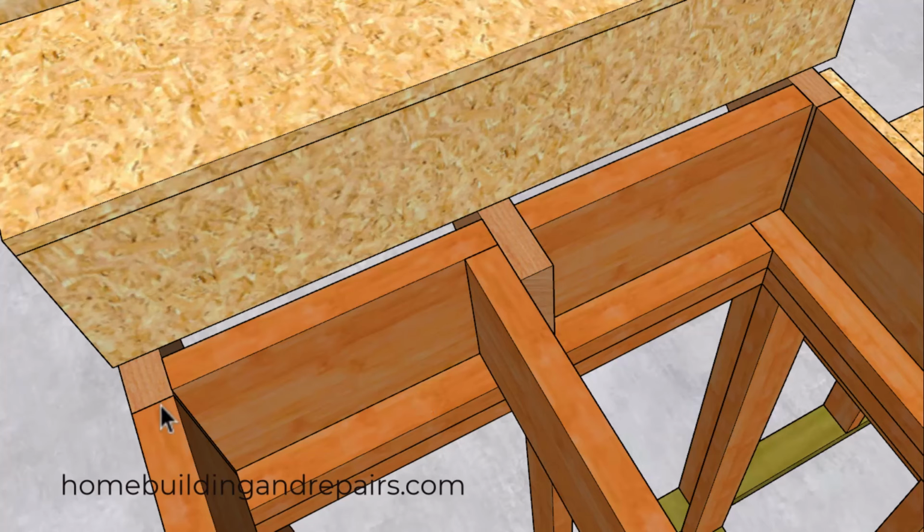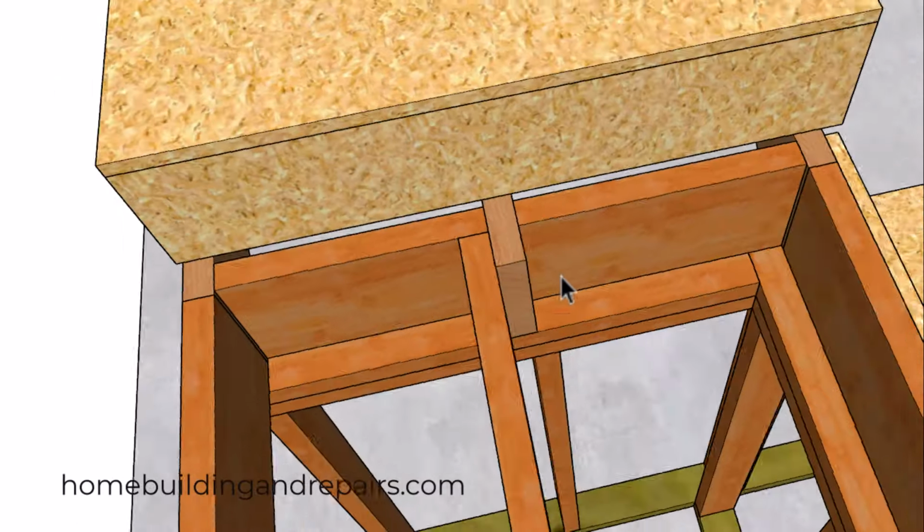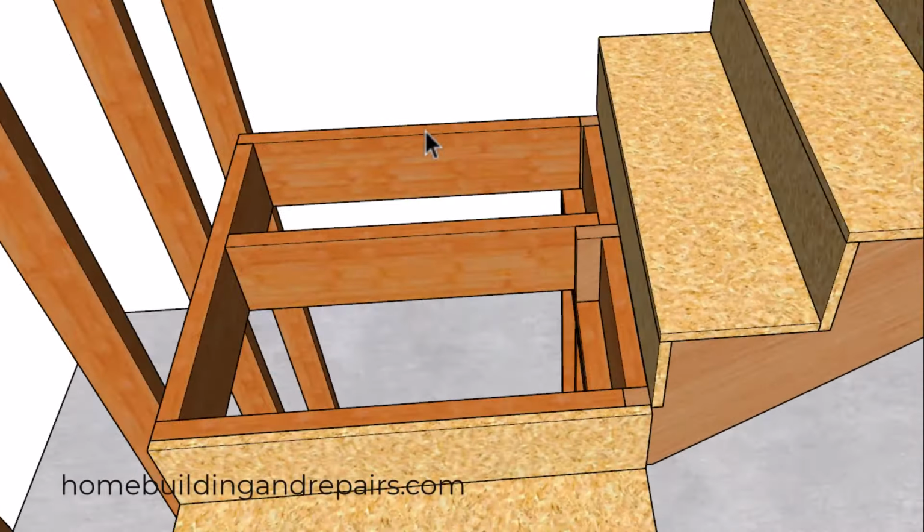And you can butt the joist to the stringer or lap them and then install your blocking. And if I was going to run the joist in this direction here, I would just simply run the joist in front of the stringers and have the stringers sit full bearing on top of the wall. So that would be like this and not this over here. And hopefully that makes sense.